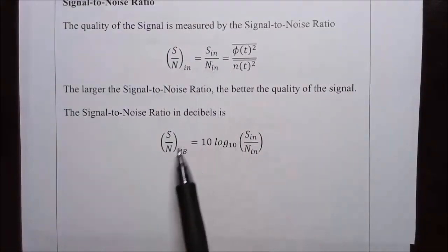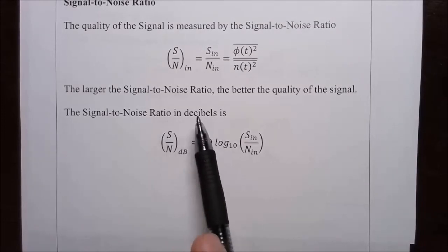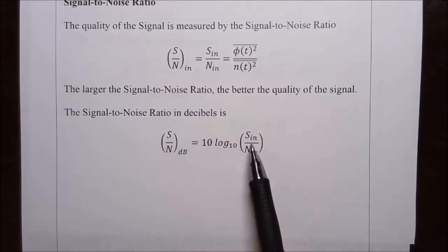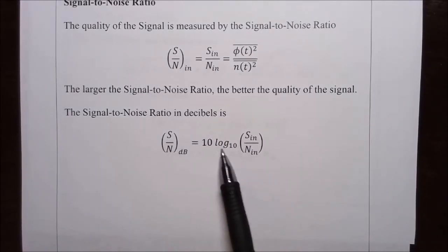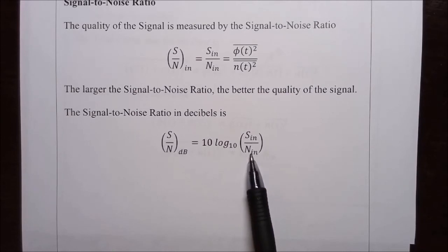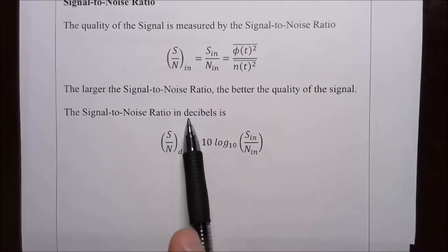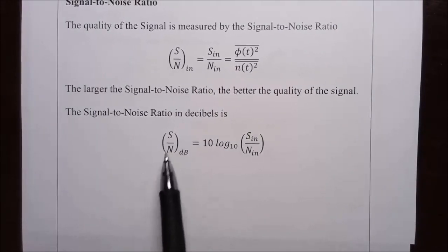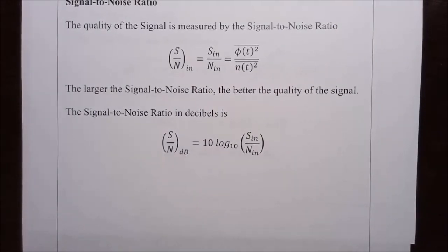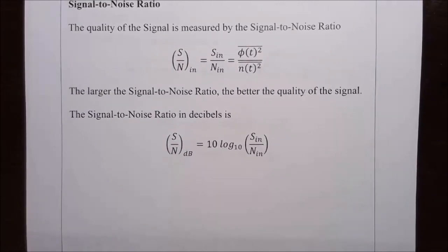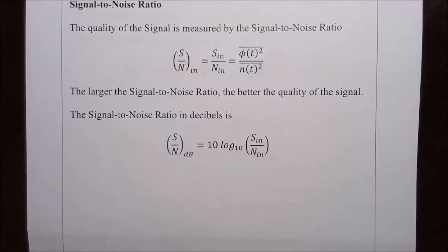And the signal to noise ratio is often expressed in decibels. So you take the signal to noise power ratio, take the log base 10, that would be in bels, multiply by 10, and that would be then in decibels, lowercase d, uppercase B for the abbreviation. And these are now the noise tools we will apply to the various communication systems.